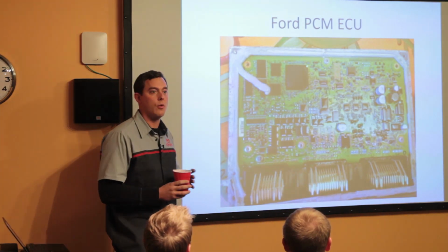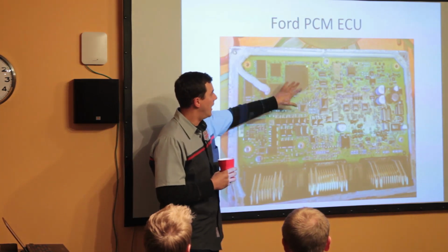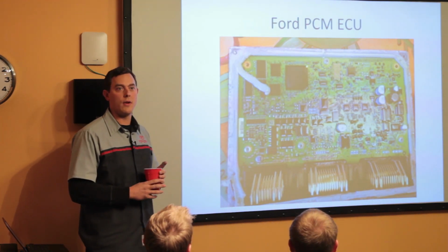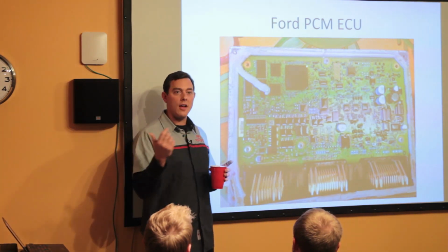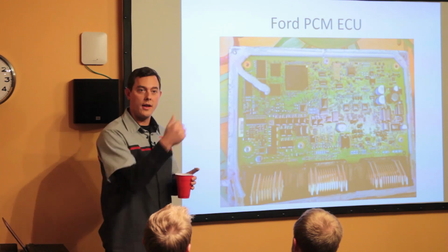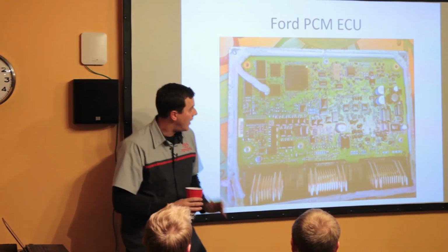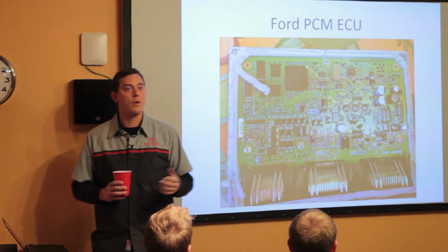That's generally what we're looking for. The circuit board has stuff covering it. I assume this epoxy-type stuff is for weathering, right? So, like rain. Yeah. But the cool thing is that you can get fingernail polish remover, and it just comes right off, so you can see the chips and what they are. We look for things like that, right? Debugging headers. Those are the type of things that we're looking for on these boards.